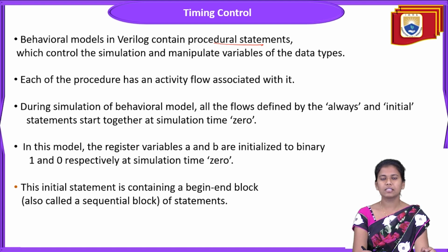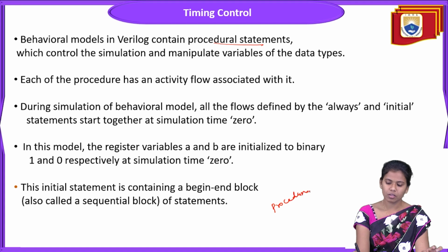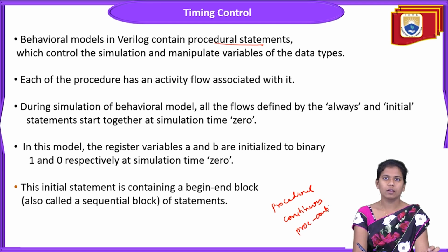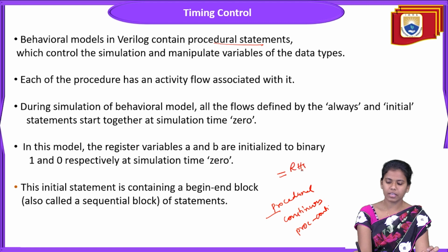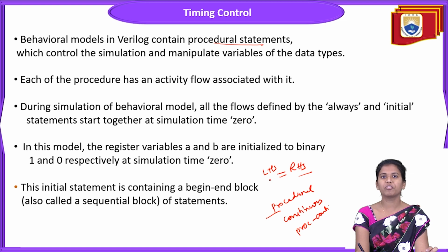We had discussed the blocking and the non-blocking assignments, and also a few procedural assignments: continuous and procedural continuous assignments. In the procedural assignment, the left-hand side equals the right-hand side expression, and on the left-hand side of the equation we will find some variables. We dump some values onto the variables. These are nothing but the assignments.